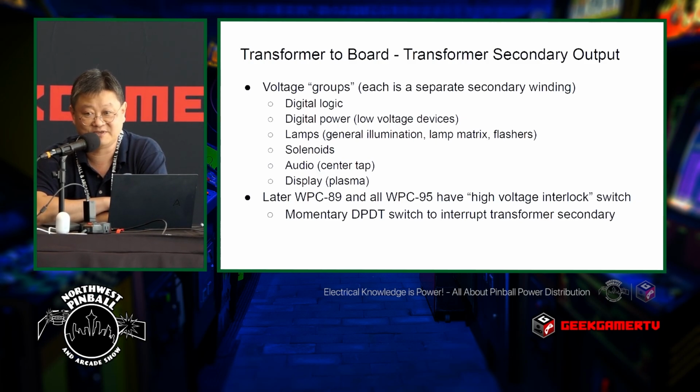So you'll often hear people say, oh, go measure the solenoid line, it should read about 50 volts. Someone goes to measure it and it reads 70 volts. And they say, is it too high? And the answer is no, because it's actually 50 volts AC nominal. And when you rectify that, convert it to DC, you end up multiplying it by roughly the square root of 2, 1.414. And if you do 50 times 1.414, you'll end up at about 70.